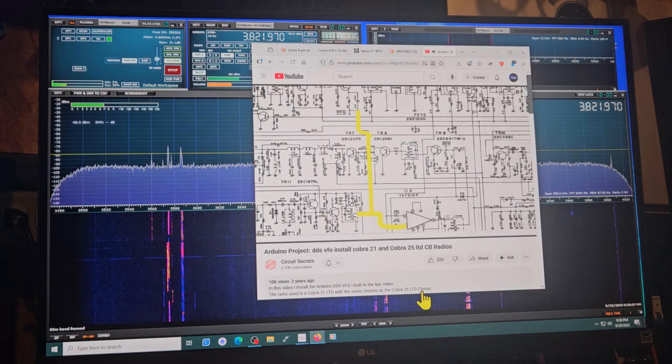A frequency from the VCO that is 455 kHz lower than the output of the VCO used for transmit is needed for receive. This is why there are 2 offsets in the variable section of the VFO source code. The PLL chip reads the output of the VCO both to adjust the output of the VCO and to provide a transmit lock feature. The transmit lock is designed to prevent transmitting if the VCO is not functioning properly, to prevent transmitting on unknown or off-limits frequencies.